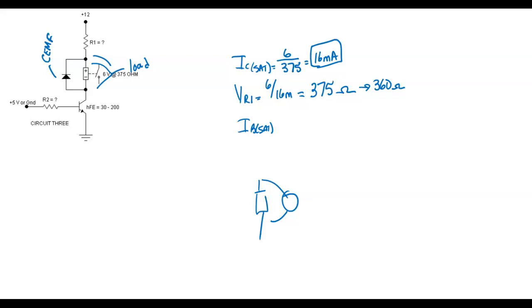It'd burn it up. So what we do is we say, okay, I need something to get 6 volts across the coil. I need something that drops a voltage with a current. What drops a voltage with a current?